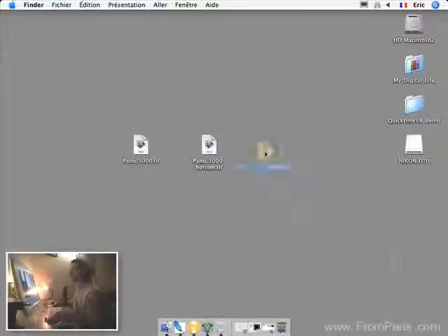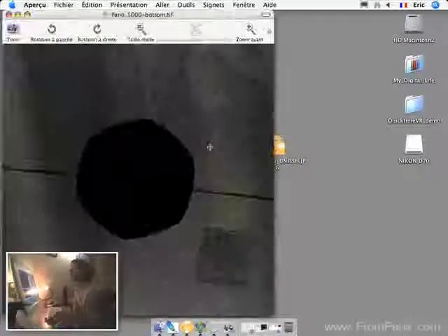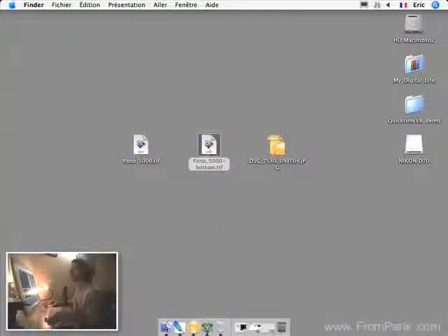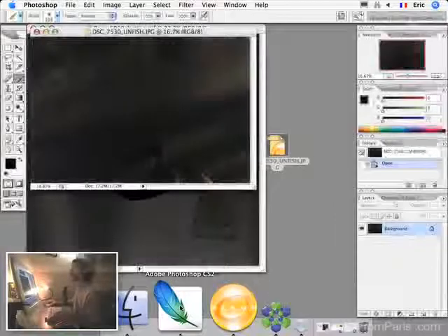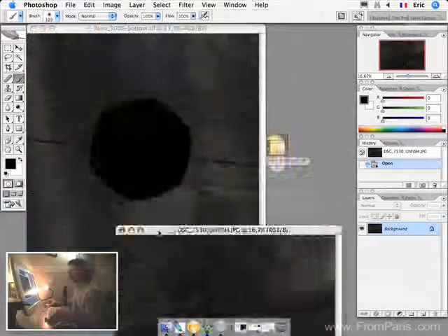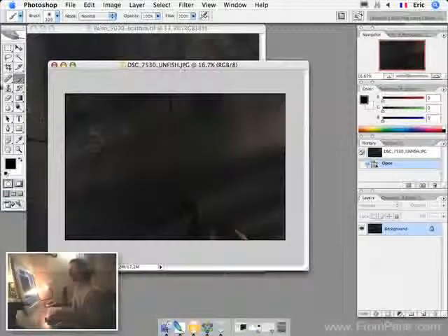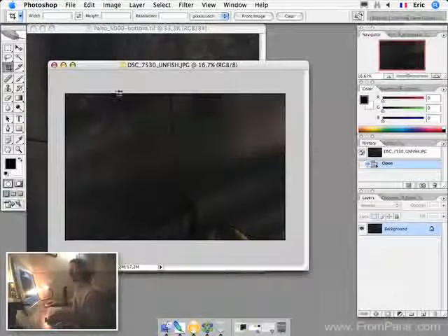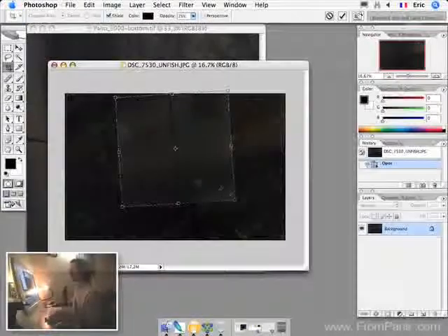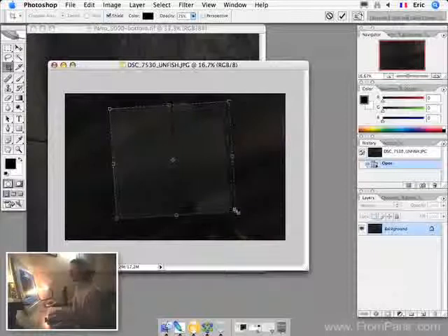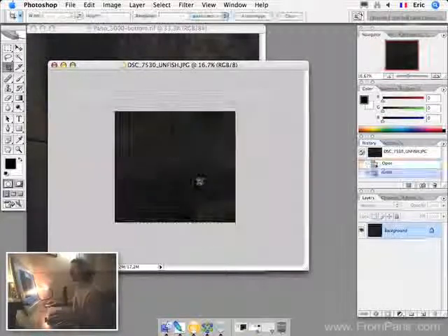We therefore now have a nadir face with the hole and a picture without distortion to fill in the hole. Adobe Photoshop and its many tools is the best software for this operation. Once the necessary area has been selected and copied, it is sufficient to put it in place and readapt it to scale.